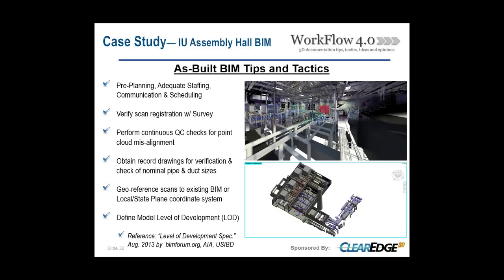And then I put it last, but I really think this is probably the most important. Chris even touched on it a little bit. Try to define before you start a job like this what your LOD is going to be. A lot of customers are still requesting BIM deliverables created from point clouds. So we're utilizing the BIM Forum LOD spec for a lot of our projects.